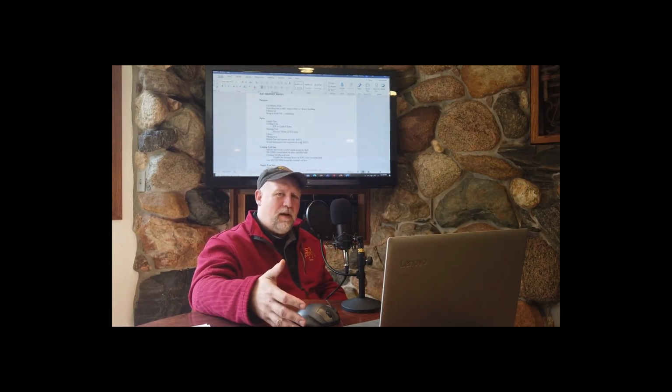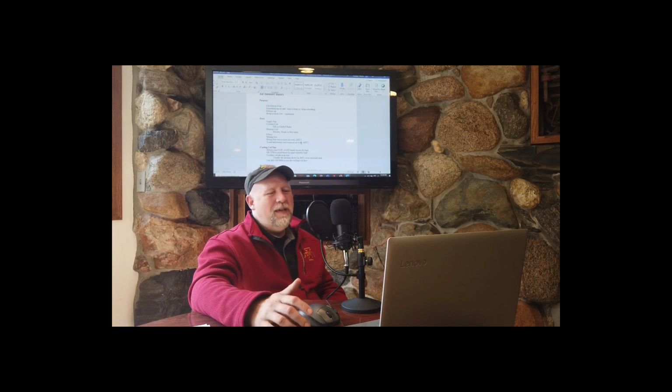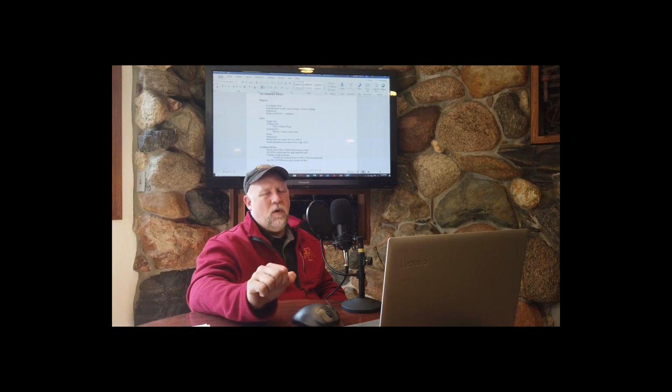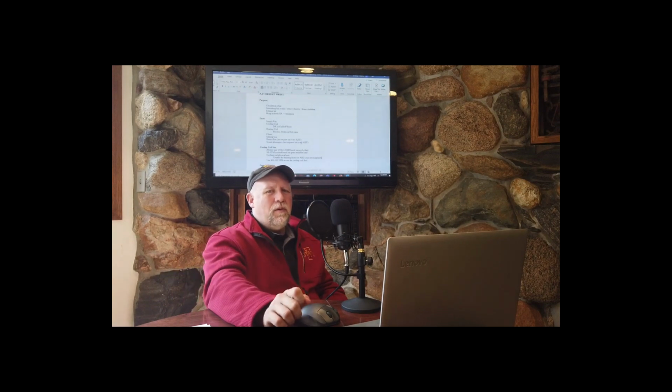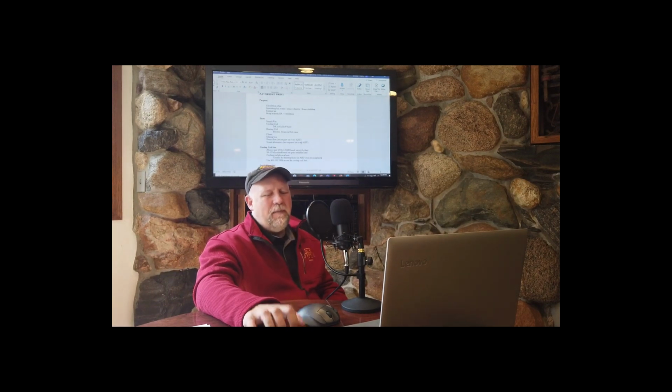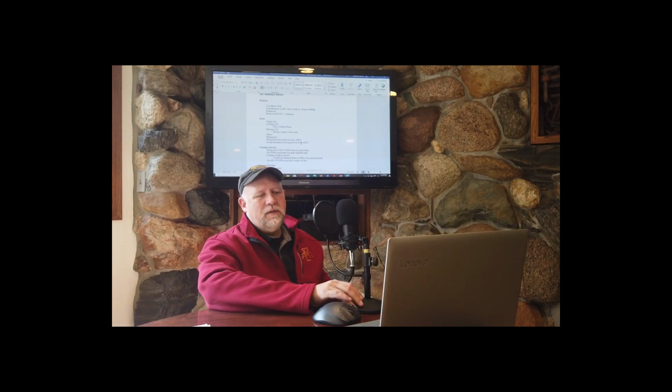Go to Town Engineering if you're one of the classrooms. Maybe if you get to a room first and there's not a lot of noise, you'll easily be able to hear a low frequency rumble. That is fan noise that travels down the ductwork and into each room. High levels of that can be very objectionable, and a sound attenuator, like I said, while not required all the time, is a good way to attenuate that noise.